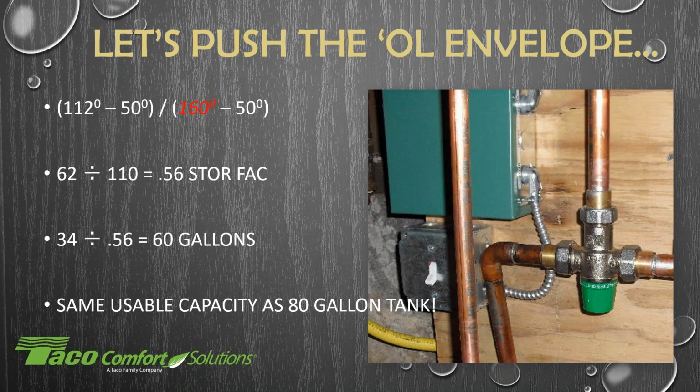Yes, I think if you start exceeding, and it depends upon the brand, once you start getting, say, over 155, over 160 degrees stored in a standard type water heater, they consider that a commercial or industrial water heater itself, and your warranties on those are a lot less than, say, a residential at 7 to 10 years. So that is some changes that happen, and they don't like to see water heaters running that hot typically.